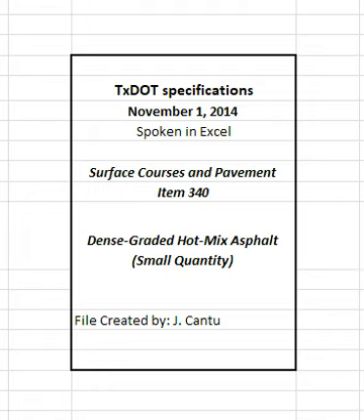Furnish the type, size, and number of rollers required for compaction as approved. Use a pneumatic tire roller to seal the surface unless excessive pickup of fines occurs. Use additional rollers as required to remove any roller marks. Use only water or an approved release agent on rollers, tamps, and other compaction equipment unless otherwise directed. Use the control strip method shown in Text 207F, Part 4, on the first day of production to establish the rolling pattern that will produce the desired in-place air voids unless otherwise directed.